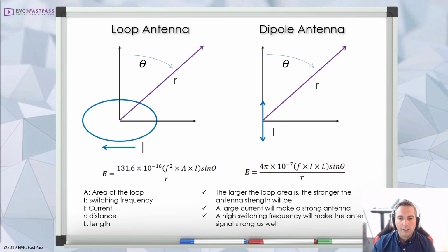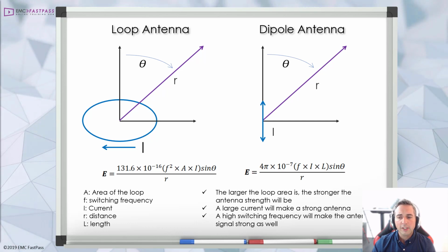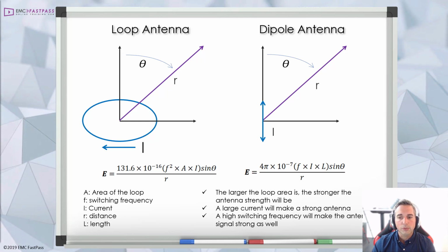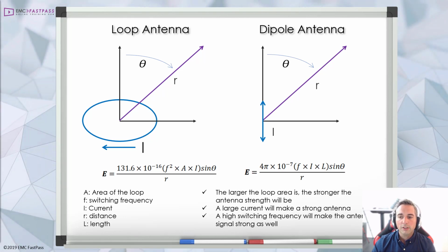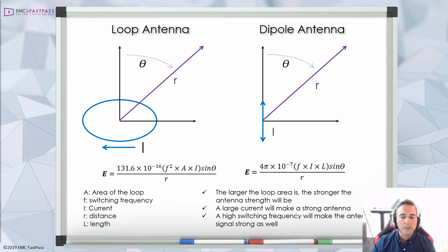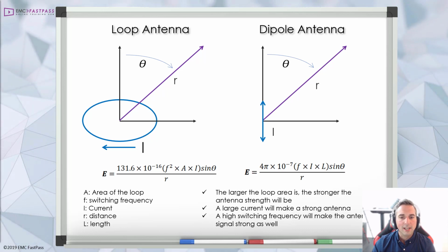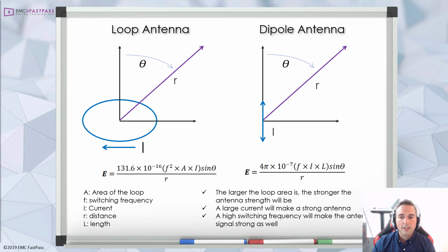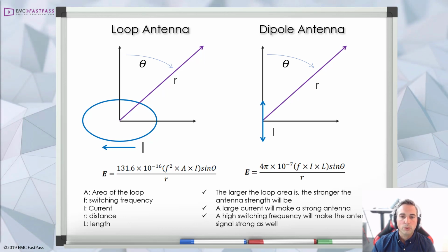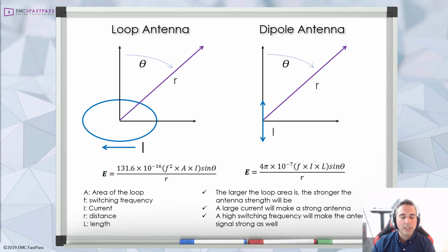Dipole antennas, on the other hand, are more synonymous with common mode currents. And they're the currents that we don't typically want to occur in our circuits or systems. Common mode currents on external cabling is one of the most common sources of emissions failure mechanisms at an EMC test lab. I just wanted to give you a heads up that these two different types of antennas can be associated with the two different types of current that we'll need to think about when we're trying to control radiated and conducted emissions.